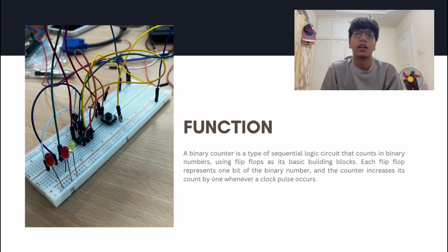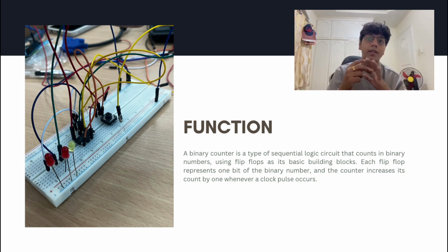A binary counter, integral to digital electronics, relies on flip-flops as basic units to count in binary. Each flip-flop corresponds to a specific bit in the binary count, forming the counter structure. Clock pulses drive the counting process by triggering incrementation through flip-flops, ensuring systematic progression of the count. This mechanism enables precise tracking of binary representation, facilitating essential functions like timekeeping, data processing, and many things in the